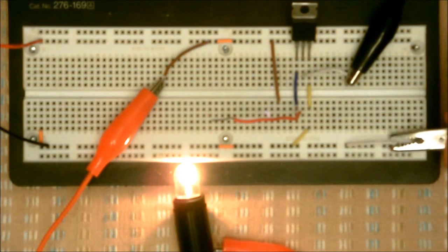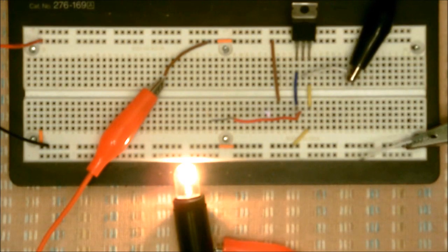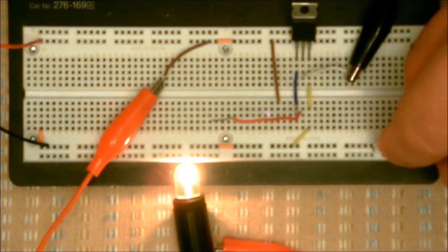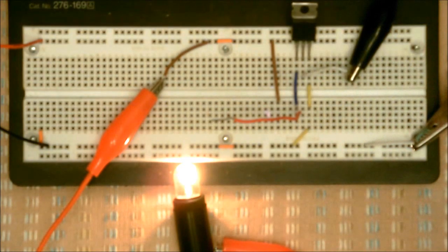So let me turn that back on, connect that back to my ground. Now, notice the light bulb is still on. The reason for that is because these transistors use a metal oxide film to insulate the gate from the channel, it creates a sort of capacitance. And this capacitance, like capacitors, will store charge. And depending on how much charge there is in the gate, it can take a while for the charge to dissipate.